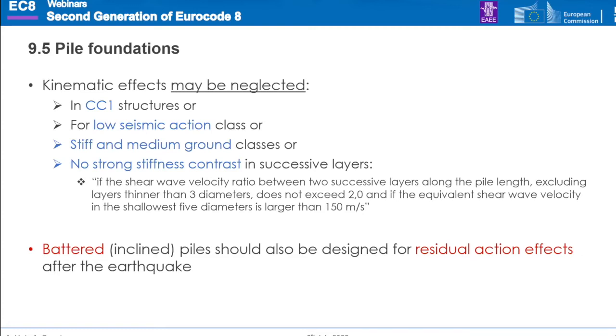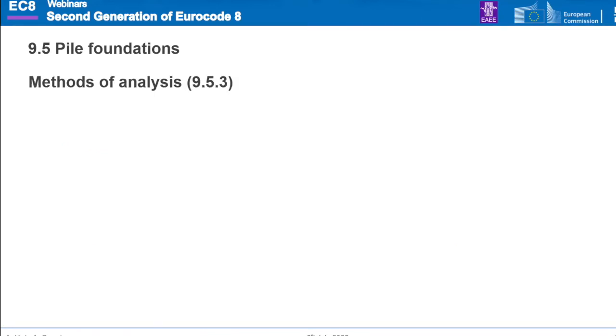For the inclined piles, so battered piles, they should also be designed, in addition to what vertical piles are designed for, for the residual action effects after the earthquake due to their characteristics.